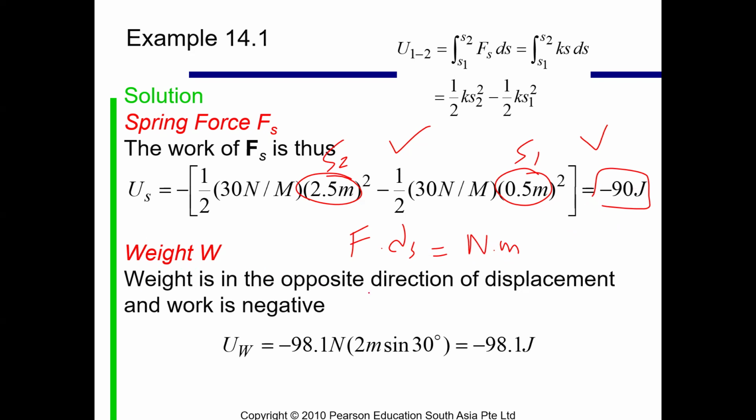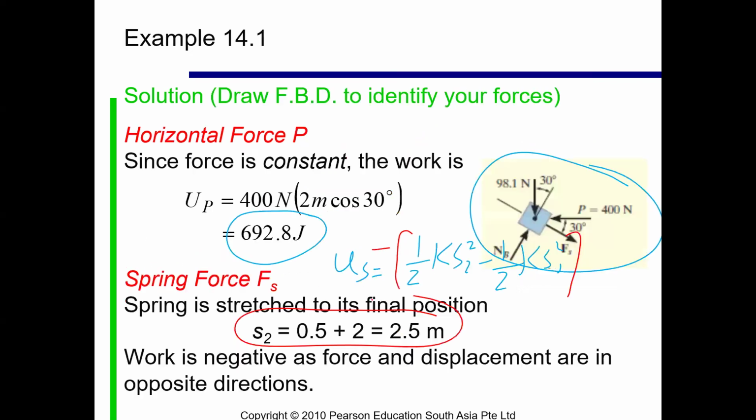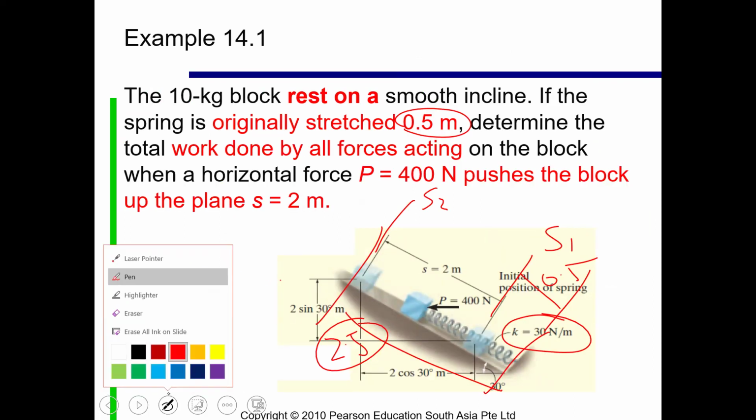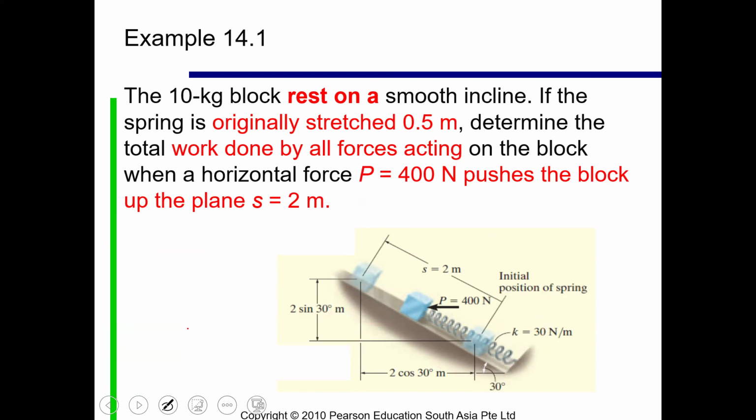If you look at the force because of the weight, again, if you go back into the scenario, we know that the weight is 98.1, right? We calculated it as 10 times 9.81. This is the weight in Newton. It is provided as a kg mass, but you need to convert it into Newton so that you can use it like a force.